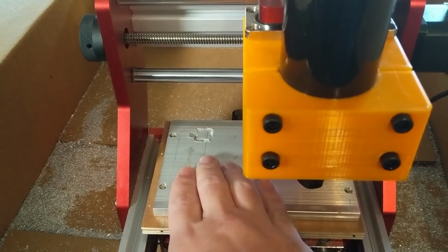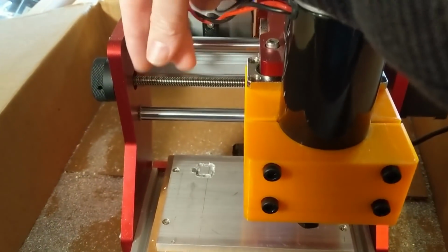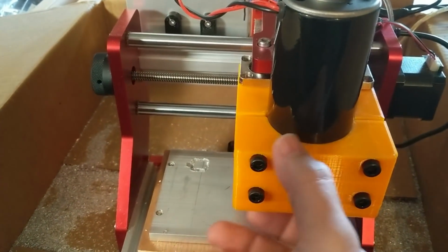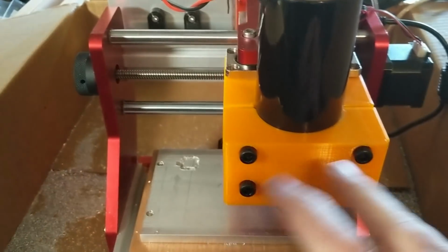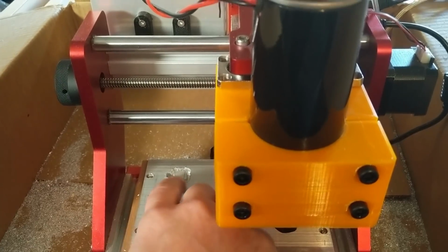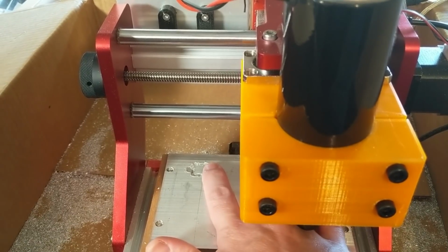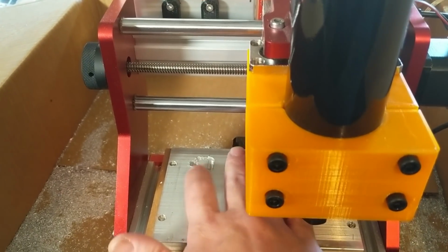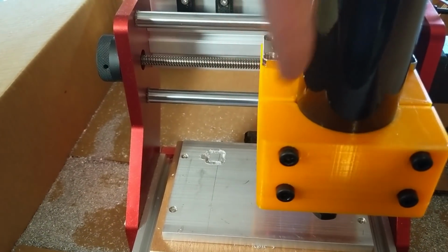The problem that I'm having is chatter. That is the number one problem, as expected from these small machines. That's why I bought this super stiff, beefy, smaller machine, hoping that I would get no flex in the machine. And I can't feel any movement in these bearings, but somehow in all of that, the bit is still sort of moving around, and I can see it moving around as it's trying to cut through the material. Now it might just be flex in the bit. It really might be just that. But there is a significant amount of vibration happening as the bit is sort of just bouncing back and forth. It's supposed to travel a straight line, and it's instead bouncing back and forth across that straight line.